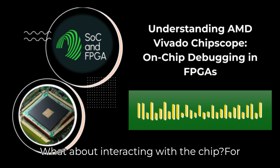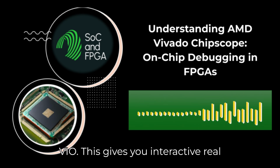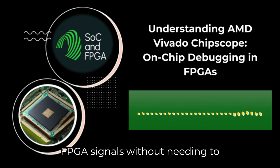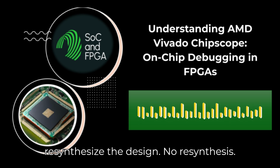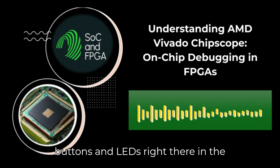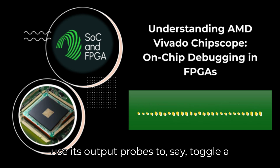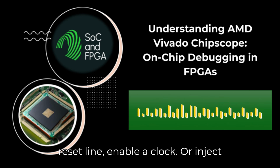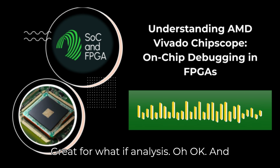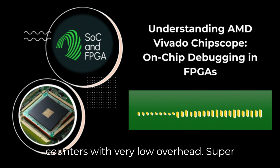Got it. What about interacting with the chip? For that, we have virtual input-output, or VIO. This gives you interactive, real-time control and monitoring of internal FPGA signals without needing to resynthesize the design. No resynthesis? How? It functions like virtual switches, buttons, and LEDs right there in the Vivado Hardware Manager GUI. You can use its output probes to, say, toggle a reset line, enable a clock, or inject some data live just to see what happens. Great for what-if analysis. And its input probes let you display the real-time state of internal status signals or counters with very low overhead.